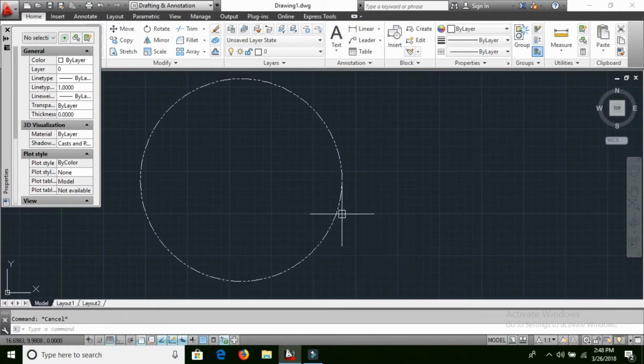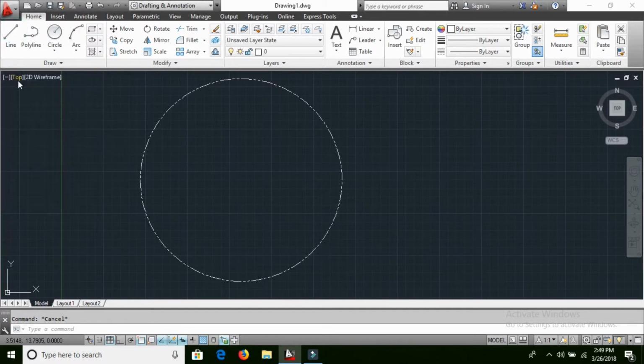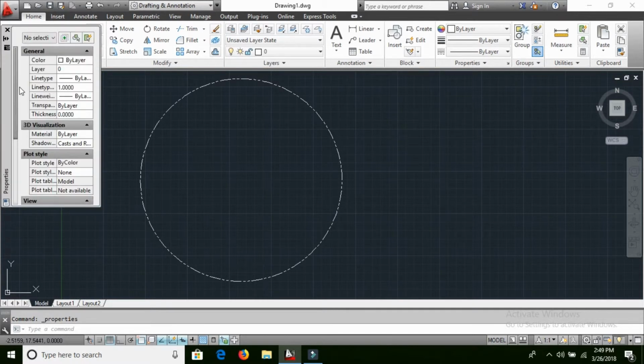See, friend, we have many different types of line types now. How we can use those line types in your plan, we'll discuss in the next command, that is the line type command. I'll discuss that with you. But in properties we can easily change all those things, that we need to remember. Okay, so that is the exact meaning of properties here. If you want to get the properties, I can also just press Control 1. We can press Control 1, so we get the properties. It doesn't mean that we have to type CH, enter, we can directly use Control 1 also. Okay, escape it, no problem.